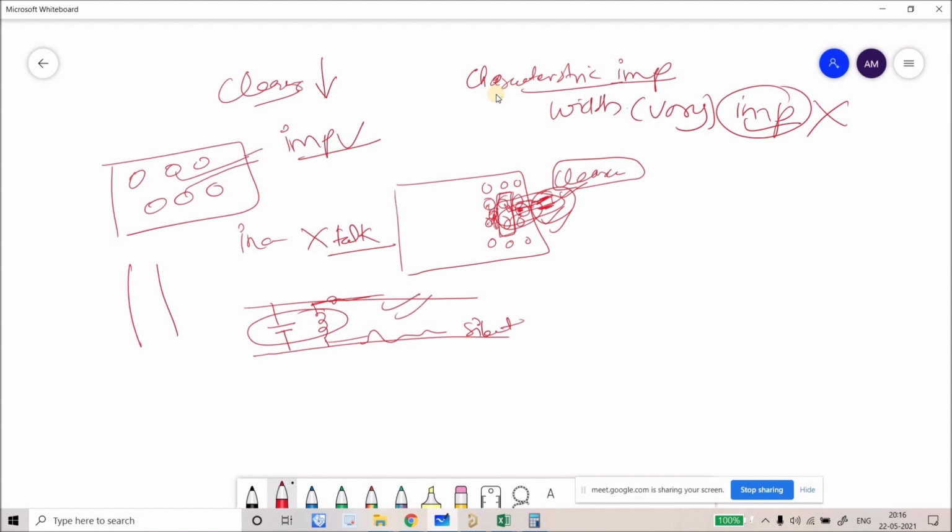If this track is functional, or there is a high frequency signal running on it, we needed this kind of coupling. Only then there will be a small amount of current induced, right? But here the thing is, our track is coupling with only this cross section. You're getting it? This is very small.